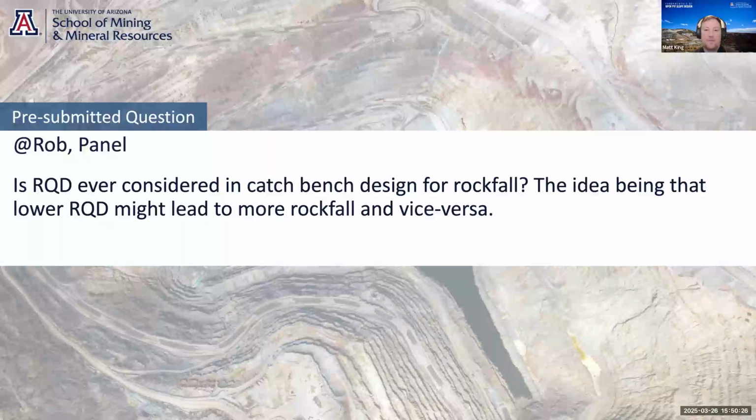I was just going to say, further to what Scott was mentioning about the double bench consideration, rather than just looking at the RQD, we'll actually look at the rock mass rating or the GSI parameter just to see what the overall quality of the rock is. And obviously the more competent the rock, then likely the better chance of being able to successfully double bench.